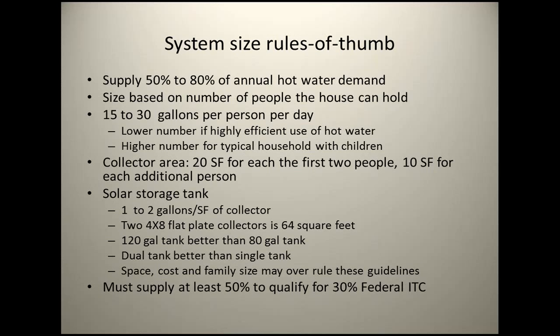You have to be careful not to close off the top of a gas water heater. You've got to stay away from the top. With an electric water heater, you pretty much cover the whole thing. The bottom level is actually very good. Yeah, you only really do the sides. And you can even double it up, though there are a lot of diminishing returns as you put the second layer on.